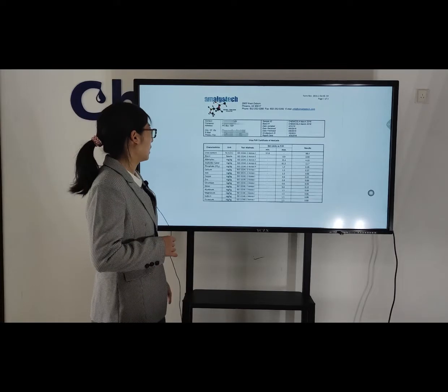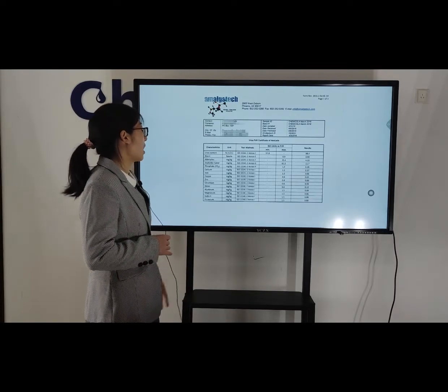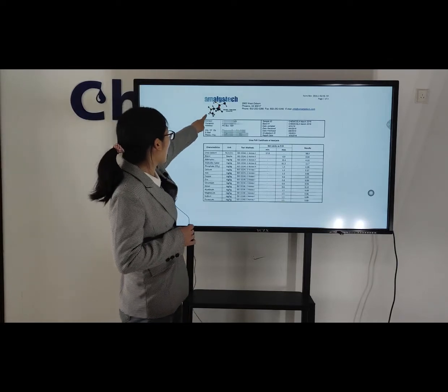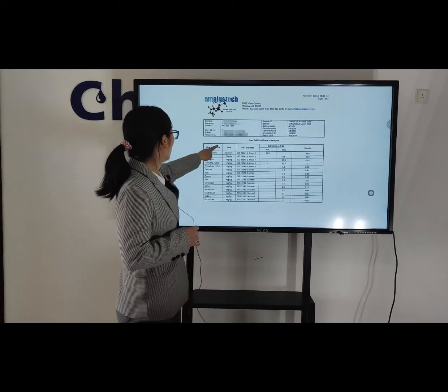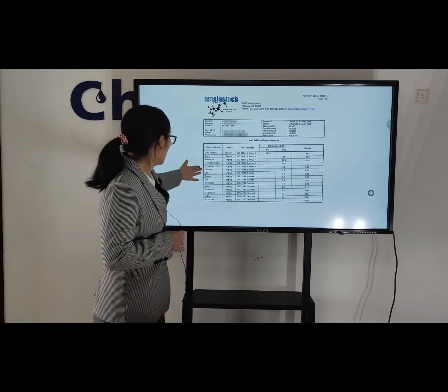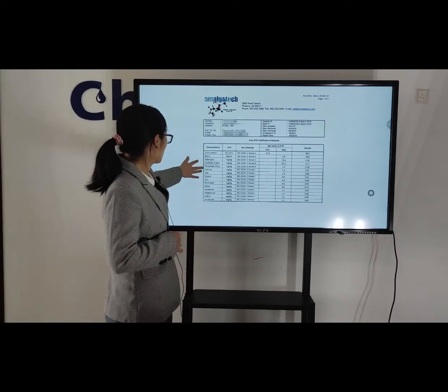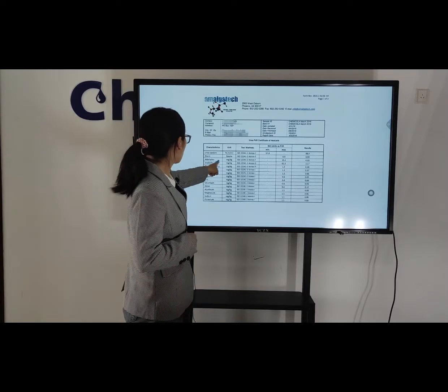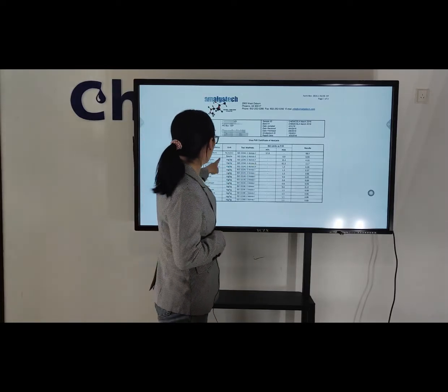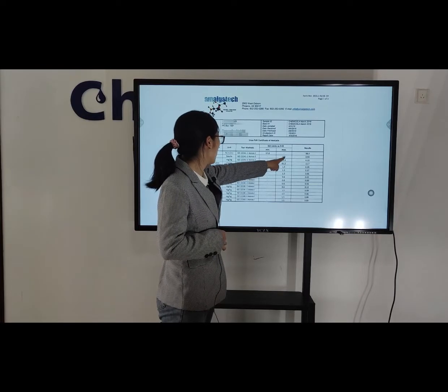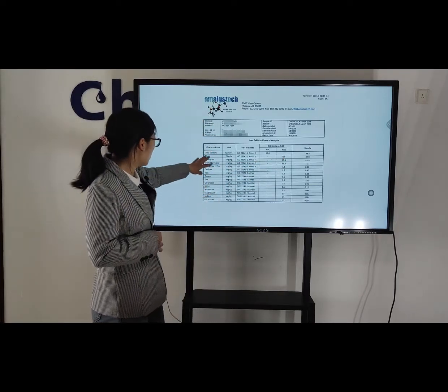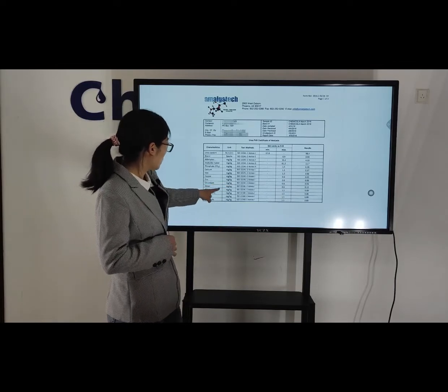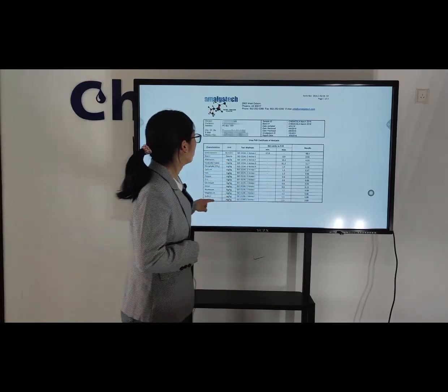Actually, since 7 years ago, many of our urea samples have been tested in this lab by our American clients. There are 14 parameters in this according to ISO standards. The key point is the biuret level, which must be less than 0.9%. All the other data is related to heavy metals, which also should be kept at a low level.